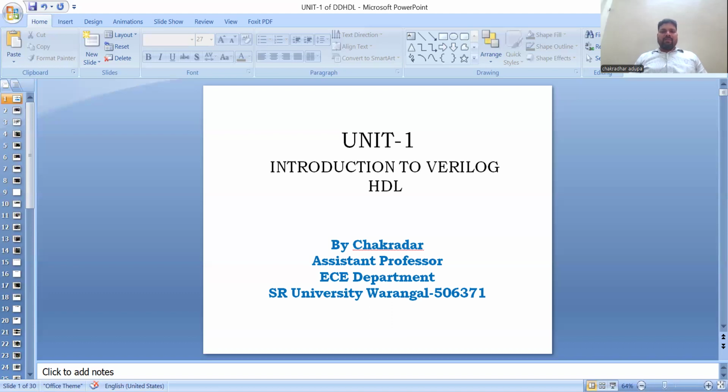Behavioral level. This level describes a system by concurrent algorithms where each algorithm itself is sequential. That means it consists of a set of instructions that are executed one after the other, and functional tasks, functions, and always blocks are the main elements which we use in the behavioral modeling style. There is no regard to the structural realization of the design.